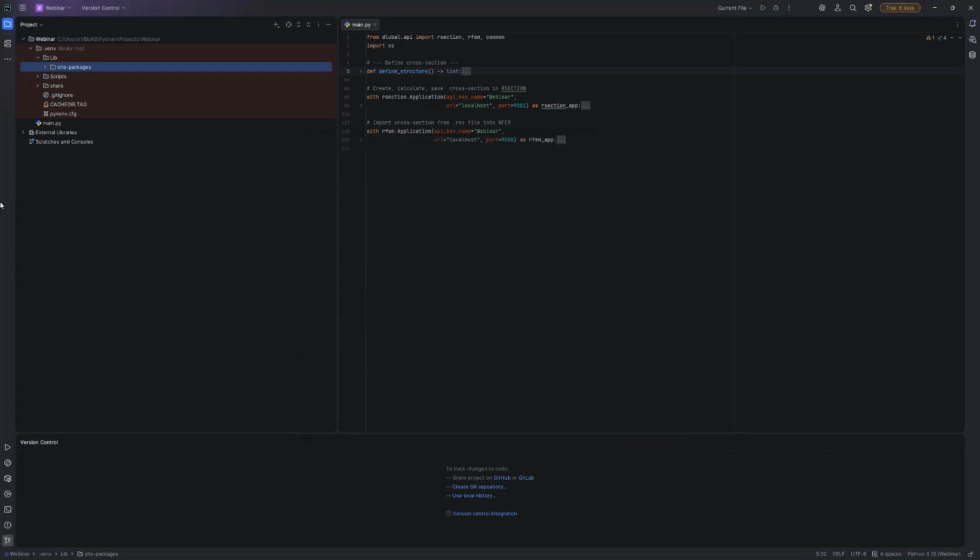Furthermore, the Dlubal API package must be installed. Make sure that the Dlubal API version matches your installed program version to ensure compatibility. For example, our section version 1.13.0005 requires Dlubal API version 2.13.5. The crucial point is that the last 2 digits, this means 13 and 5, of the version numbers match.